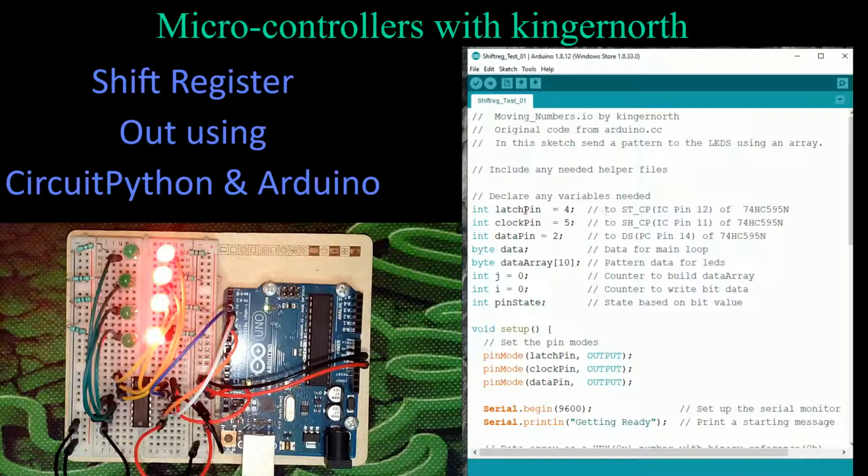And the other two here are what I call the latch pin and the clock pin. One is setting the pulse, and the other one is sending whether the value is going to be either 0 or 1. That's the binary value to set to that particular output at a given time. So the information coming in about the latching is going to happen on pin 4, and the clock is going to happen on pin 5. The clock is just that steady pulse. As it sees each rise of the clock, it says, okay, what's my latch pin? Write that into the buffer on the chip, and we'll go through that in the program.